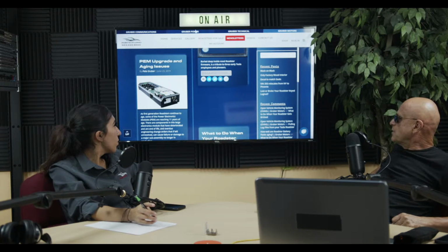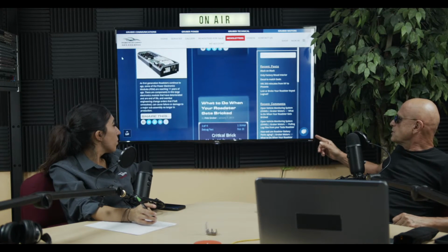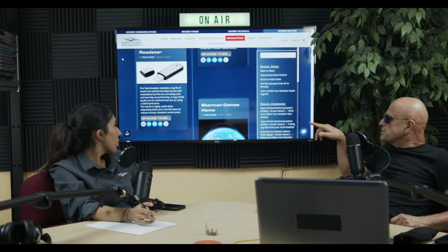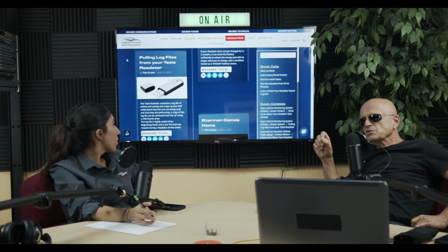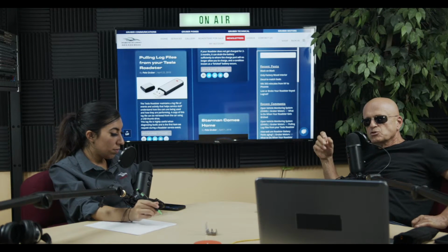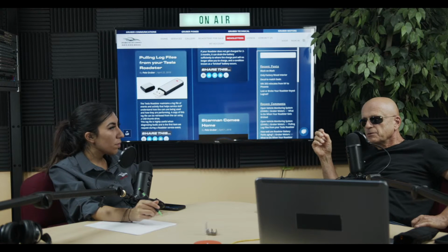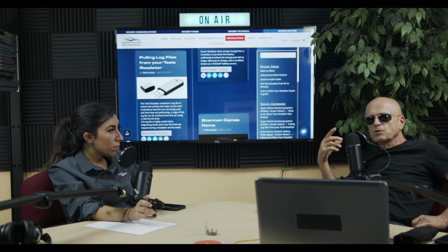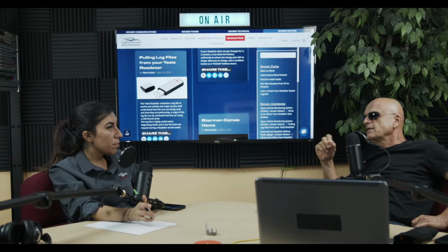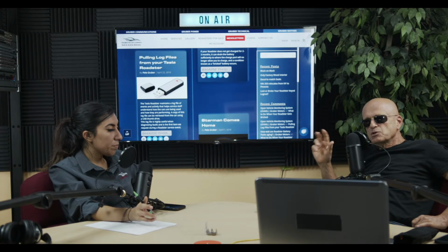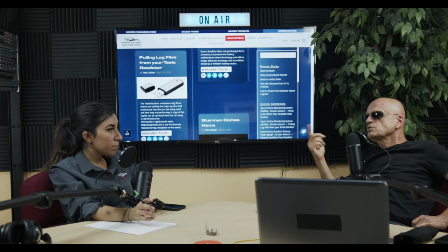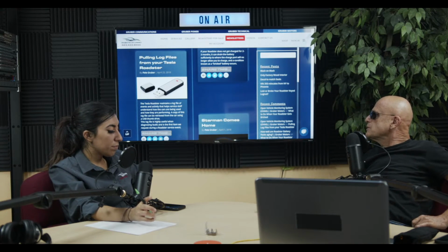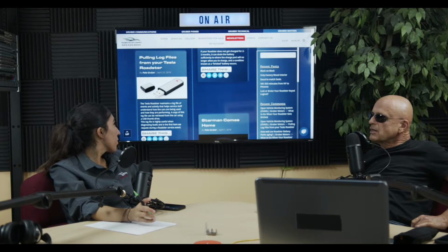So what do we have next? I think we've gone through that, what to do when your Roadster gets bricked. So let's keep going. Pulling log files. This is also a good one. This is used often at the service centers. There's a procedure. There's a certain type of memory stick that you have to use, and then you have to put a file in that directory, and you have to name it precisely, upper and lower case. If you skip all of that, you won't get a log file out of the Roadster. So this newsletter gives you exact instructions on how to pull your log file.